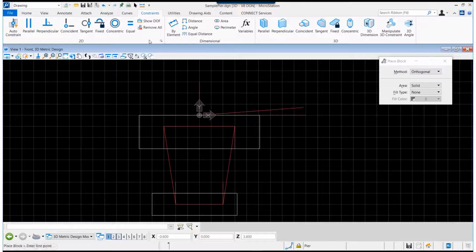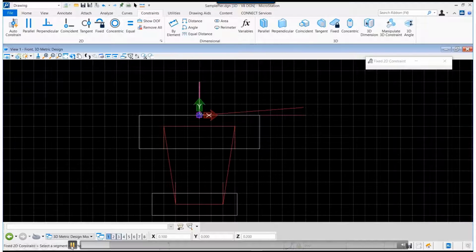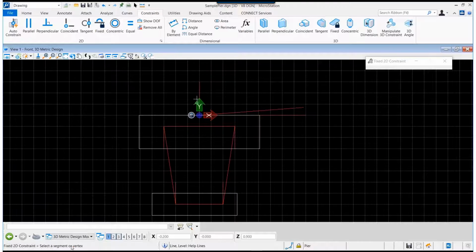So then I establish the constraints. What is that? Meaning how these lines are going to move. So for example, this point will be fixed according to this line, right? And then some elements, as they move, will always be coincident with the elements that they are attached to.